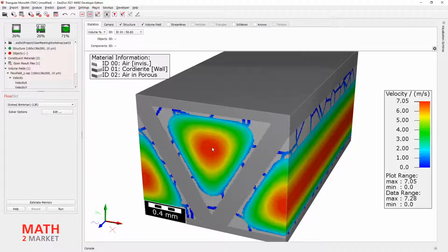And this is totally normal because the mean velocity is calculated over our whole surface area. But there are for sure some places where no flow is possible. So here the velocity is 0 because we assume that there's no flow here in our monolithic structure. There's only flow in our washcoat. So to have a mean value of 2 meters per second on this whole surface, there surely have to be some points where there's a higher velocity, and this is much higher than the 2 meters per second that we have specified.